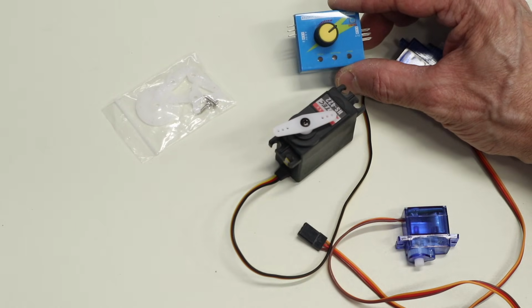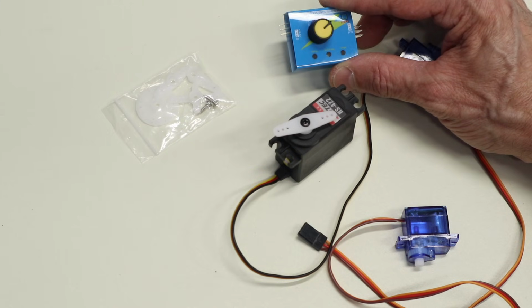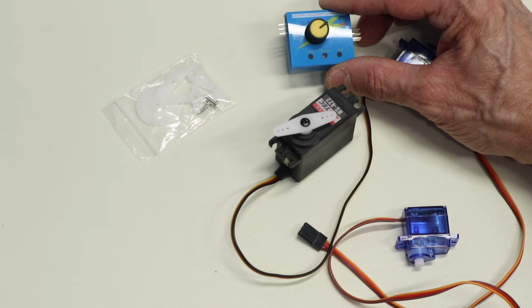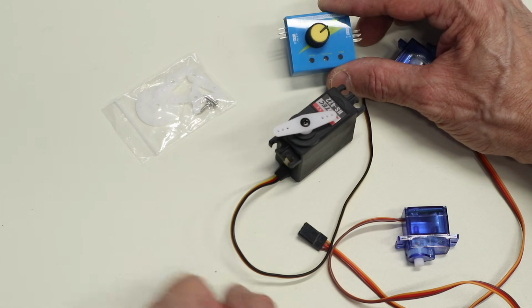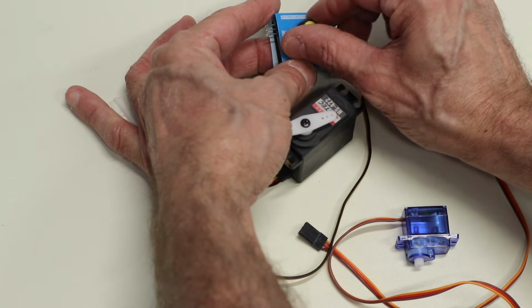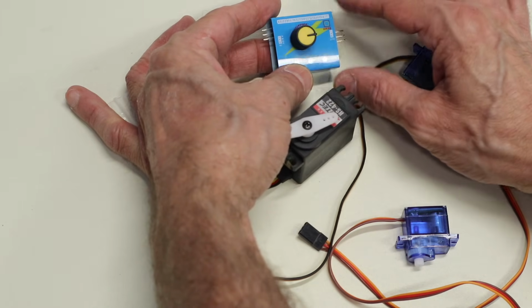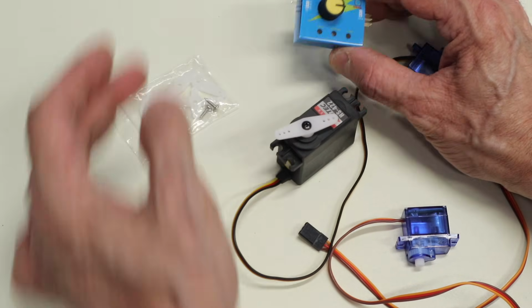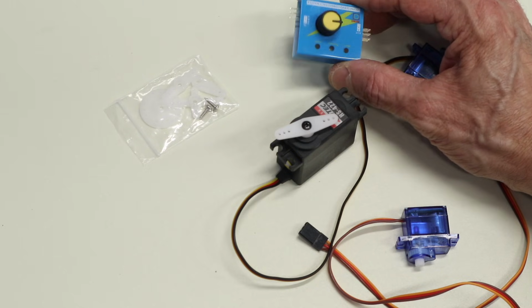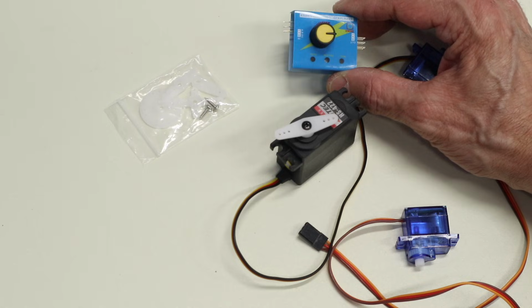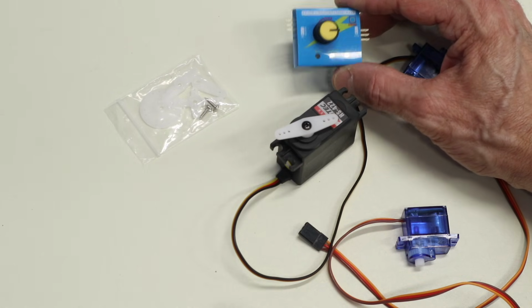Now over here I've got a little device that I picked up. I think this was literally about $2 or $3. They're very inexpensive and they're called servo testers. Again, Amazon and eBay are great places for them, and they allow you to test out servo motors. You apply power on this side, connect your servo on that side, and you can use this knob to determine the position. It's also got a couple of other tests you can do, like homing the servo, etc. And these are very popular with radio controlled hobbyists who use boats or aircraft that have a lot of servo motors. They carry one of these with them just to make certain their servo motors are okay.